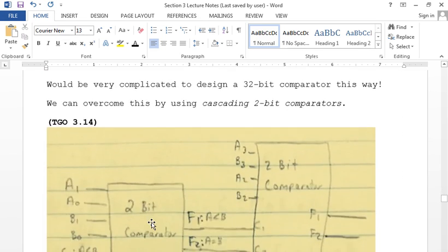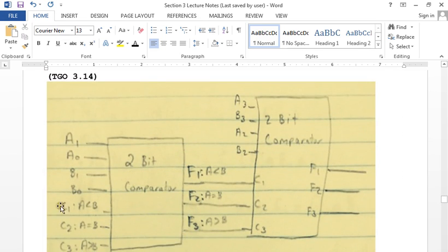Based on that, you have these set as 0, and now we can cascade it further. When you're talking about anything with a comparator or a multiplexer, the analogy I gave to some people in the lab is to think of it like a basketball tournament. A 32-team basketball tournament: we select 0 or 1. If you lose, you're 0, you don't pass. If you win, you're 1, you pass on. So you use a multiplexer to take it from 32 to 16, then 16 to 8, down to 4, down to 2, down to the national champion. The comparator does the same thing.